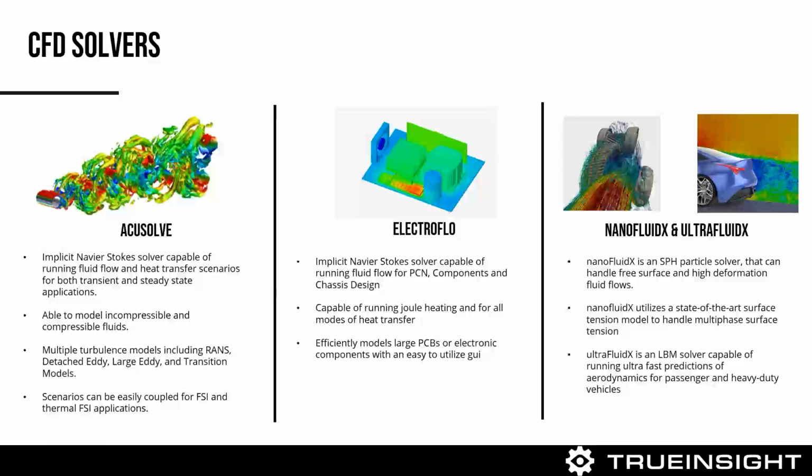Electroflow is an example of a finite volume solver. It's another implicit Navier-Stokes solver, but it's really geared towards chassis design, boards, and lots of components for PCBs or joule heating. So if you're dealing with any type of electric thermal analysis, this is a really powerful CFD solver that can handle that.